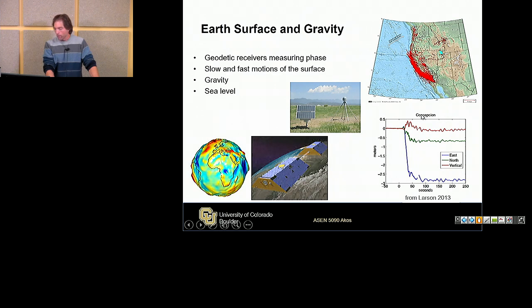And this is Concepcion, basically when they had an earthquake. And you can see GPS is measuring the displacement, east, north, and vertical. Very, very quick displacement, fairly significant when you have an earthquake. So PBO is really looking at plate shift tectonics on a carrier phase level, very high accuracies to see what happens, and GPS is a key piece for this element.